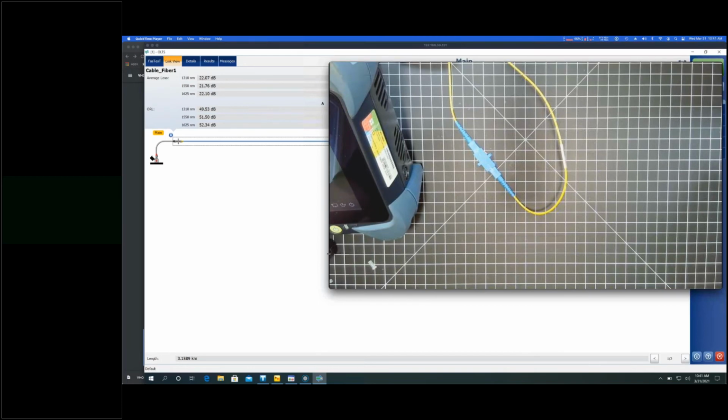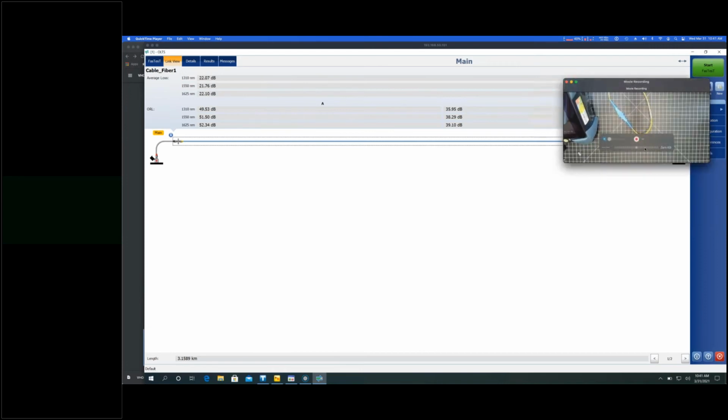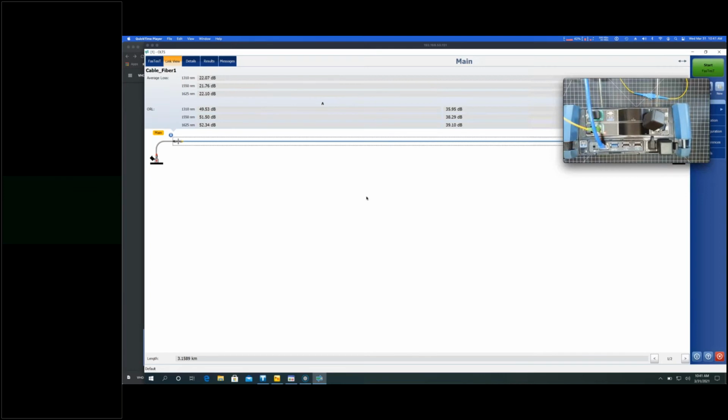So the last method I want to talk about is basically the same, very similar, but we're going to use just the equipment that we have on board on the OTDR. So if you have an EXFO unit, usually we will recommend, and I would say in most cases, unless you just need the very most bare bones unit, we definitely recommend having an onboard power meter and VFL.